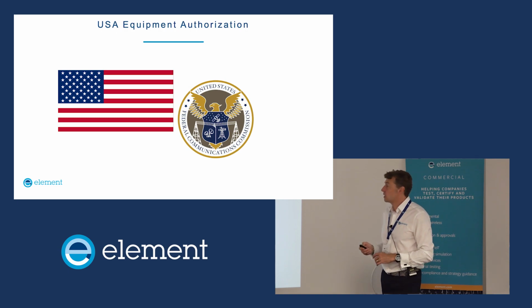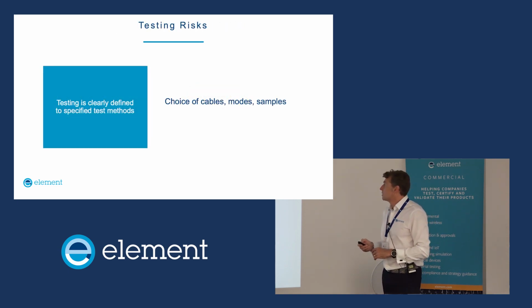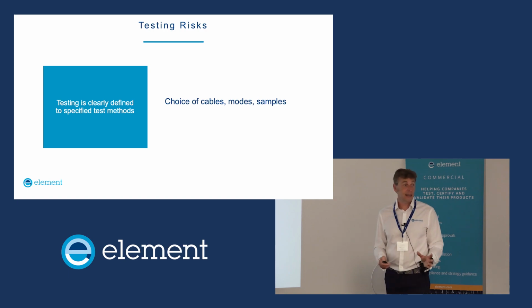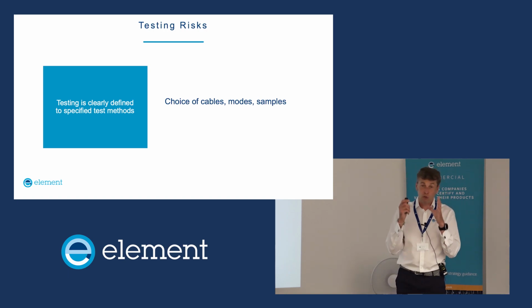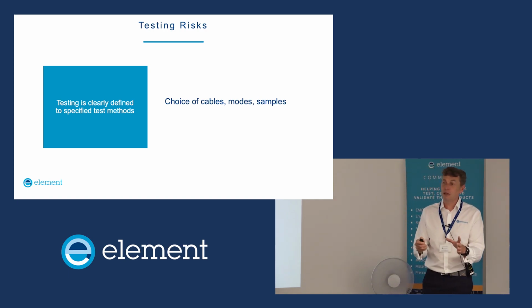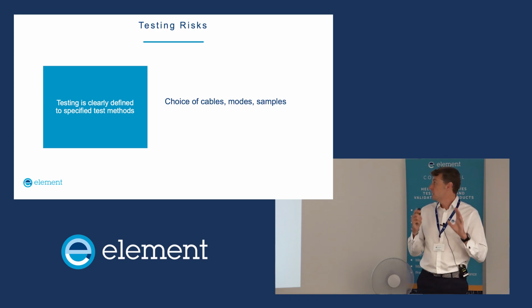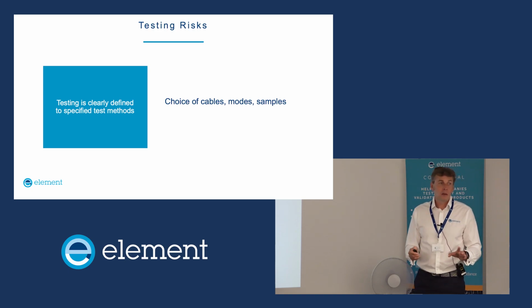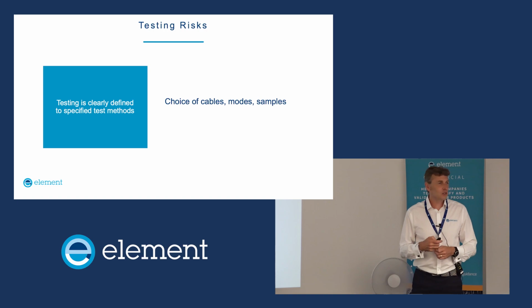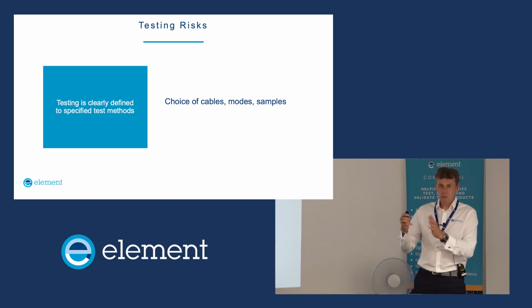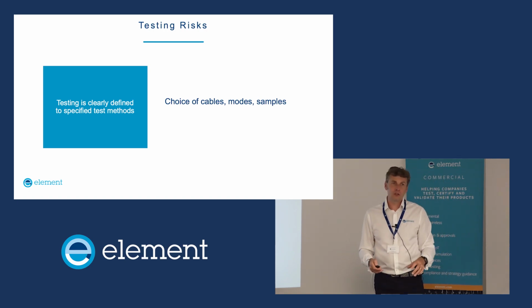So let's have a quick look at the USA. Testing is clearly defined in the standards. It says, right, here's the standards, here's the test method, do not deviate from it, do the right thing. But then for things like cables and test modes of operation, it sort of says set it up the worst way that you know. So it's quite subtle in its way of saying you must test like this once you've set your product up in the worst possible way.